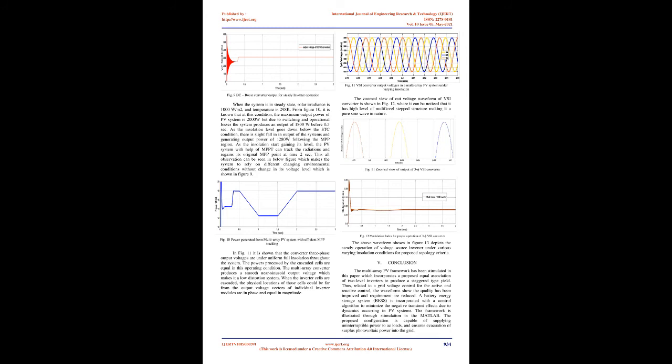maximum [21]. The battery side inverter is also controlled by a grid voltage-oriented control similar to that of the PV. The active current reference, I*Q, is derived as the sum of the charging current component. As shown in Fig 7, the PI controller for battery charging is used to ensure that the sum of the real power produced by the battery and PV is maintained at a specified reference value, such that the battery only supplies the amount of real power lost during shading of the PV panels [22-23].